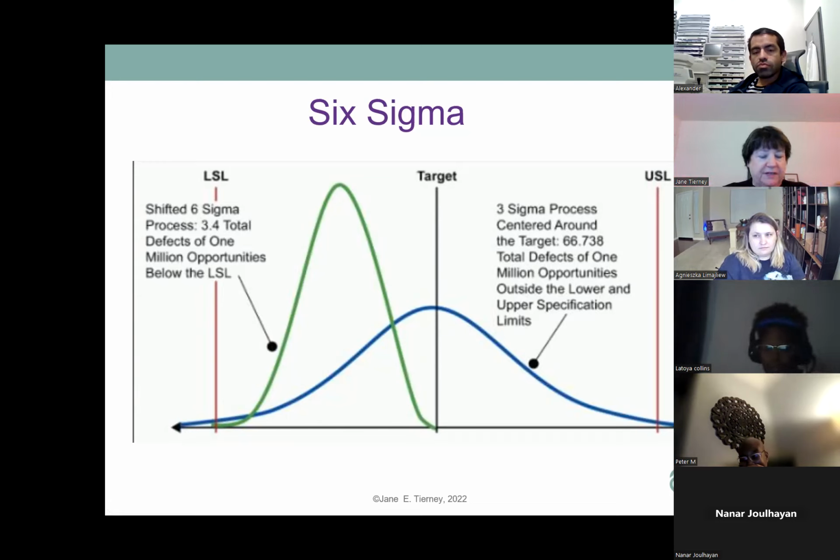So what we do with statistical process control, or Six Sigma, is we use a charting process, and we chart these and we calculate not specification limits, but we calculate control limits. So we want to say, how good is our process? How repeatable is it? How frequently do we get parts in the right range of dimensions that we want? And how far apart do they vary?